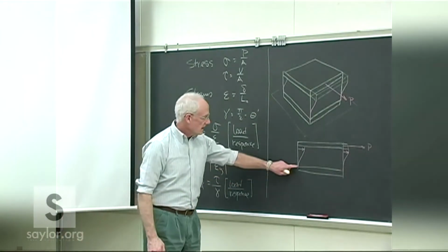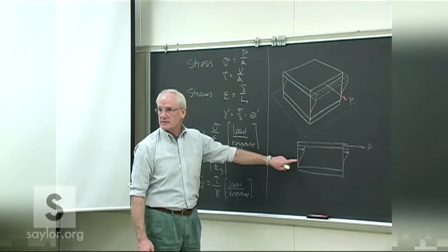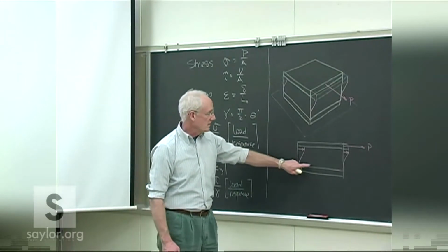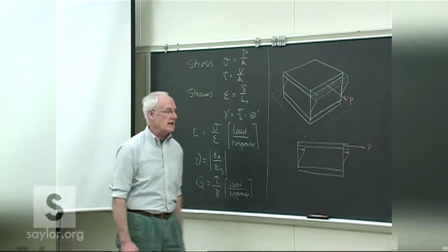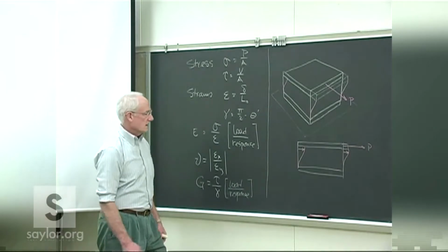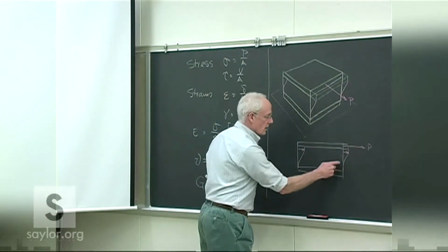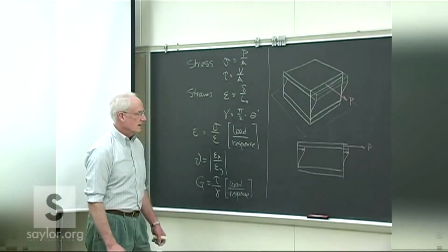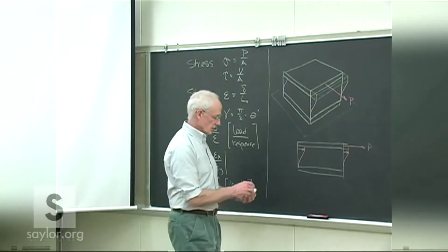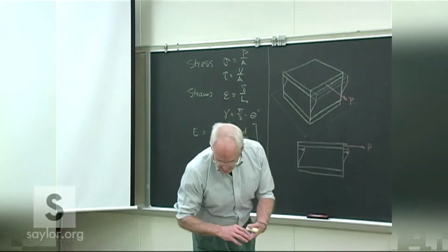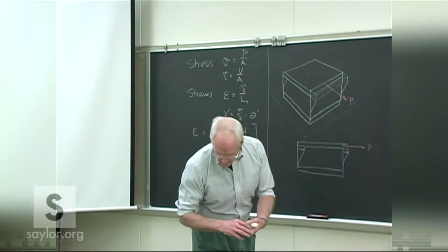The reason it's a curve shape like that is because the bonding of the shear block to the plate would cause the block to actually have no slope to it there, and then the entire center section is absorbed by the slope, or absorbs the load.